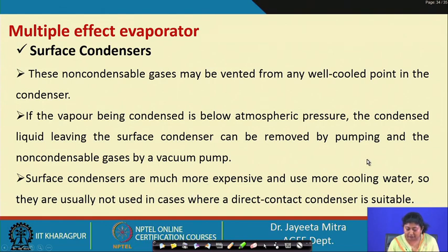Because we need to take them from the low pressure to the high pressure, the condensed liquid, that is why we need to pump them. Okay. Then surface condensers are much more expensive and use more cooling water. So, they are usually not used in cases where a direct contact condenser is suitable.